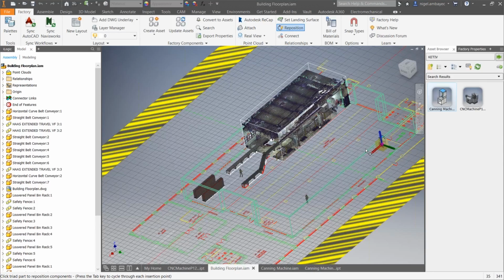Can the manual tasks be animated and performed by the operators in factory? So that gets into a little bit of like the not 101 level stuff, let's say the 301 level stuff, where you can start doing some of those animations using things like Navisworks or maybe even 3ds Max to kind of animate those actions made by the people in your factory or those machines in your particular facility.